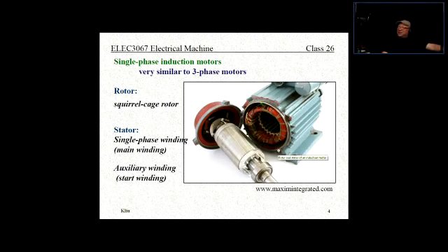If we don't have a variable frequency drive in the lab, I would use 3 DC generators to control the input frequency and the voltage of the 3-phase induction motor. Answering the last class question. Thank you. So that means you're paying attention.